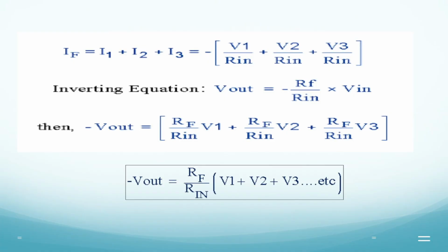You can also have an inference from the previous inverting amplifier. Looking at the negative terminal, whenever you give any input, it will give a gain of minus Rf by R1. Now you have 3 different resistances here. If you go on with the analysis, Vout divided by V1 will give you Rf by Rn. In the same way, Vout divided by V2 will give you the same Rf by Rn. Since all the resistance values you have provided are the same, the gain is also the same for each, but the input voltages you have applied are different.